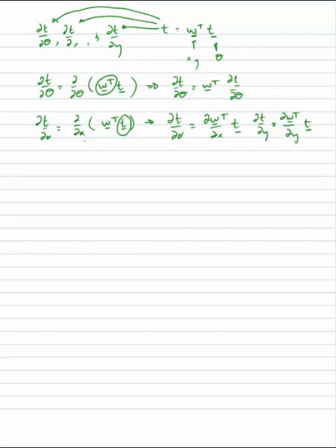So I'm going to take now this, this, and this, and substitute them into the weak form of our finite element equation, and we get then the integral over the area of F times rho C times d temperature d time, which is this right here.